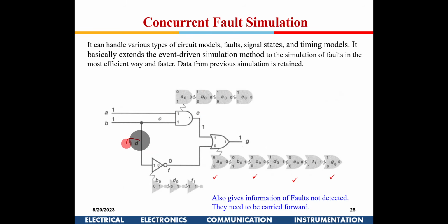and I am taking a fault at D, so this will be 1 from here, whereas in D I am taking it as stuck at 0, so this will become 1 here, so that will not get detected here, right, because a 1 is coming from here, so the actual required is also 1, so I don't get a difference. So this fault cannot be detected.